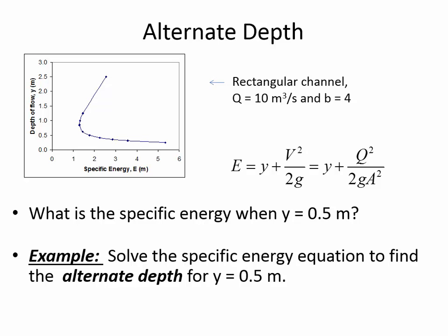Well, 1.66. Our guess was 1.25. Let's take a second look at that. So 0.5 up here. Okay, yeah, it is 1.6. So that's a good illustration of why maybe you'd want to not rely on the graphical method and do the calculations instead. Okay, so this is our alternate depth. Who can rephrase, what does this mean? Who cares? What's the significance of 1.66 meters compared to 0.5?